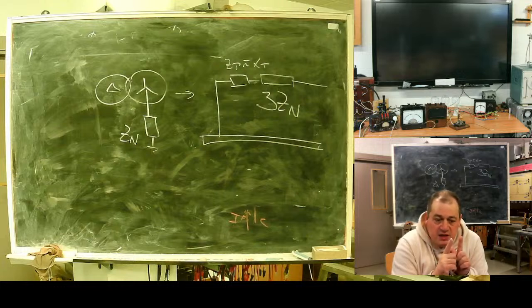If you're lucky, it will be already estimated for the lines, maybe in the form of a mutual inductance coefficient. But if you're not lucky, you need to calculate it. The same Carson's model will work for 50 or 60 Hz. But be careful.